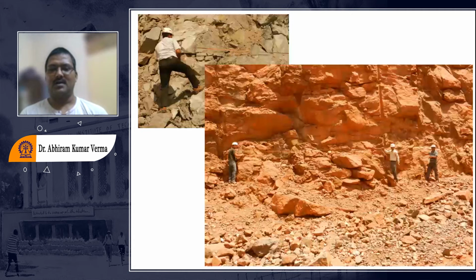You can see signs of holes. Possibly some blasting has taken place, and because of that the rock mass has fragmented. So we have to see whether there is any sign of discontinuities. We cannot consider this mechanical break as a joint. This is very important for us to understand.